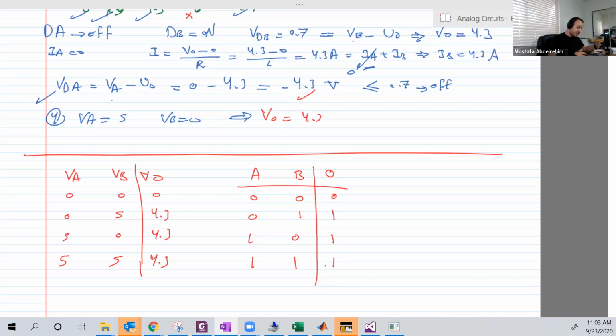So now this is another logic. This is called OR logic, in which if any condition is satisfied, then do the action. Of course, if both are satisfied, also do the action. In AND logic, both must be satisfied in order to do the action. So only the last output here with 1, 1, when both conditions are satisfied, is 1.